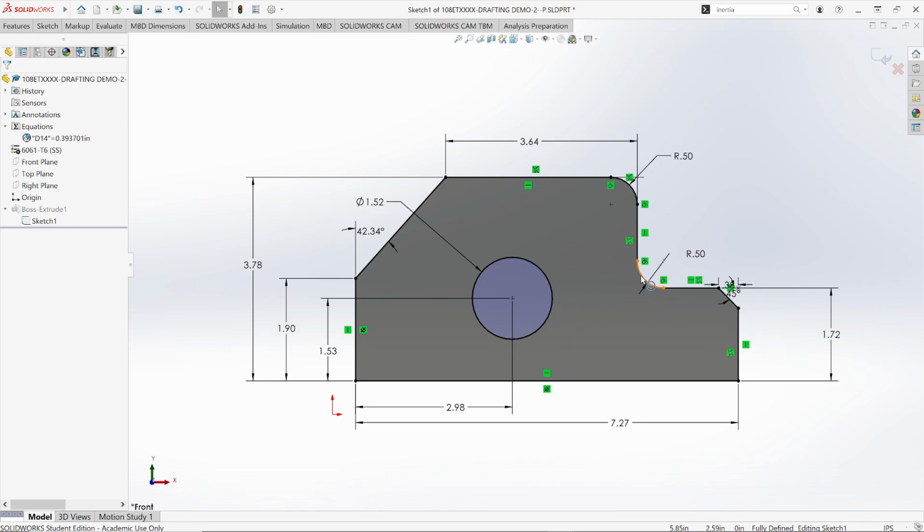We've put in the corner and the round and the chamfer, so I'm not even going to worry about that. I'm just going to count up the dimensions. 1, 4 out here, 3, 4, 6, 7 dimensions total. Now, careful, don't just go jumping out of here. Make sure to exit the sketch workbench, otherwise it gets confused.